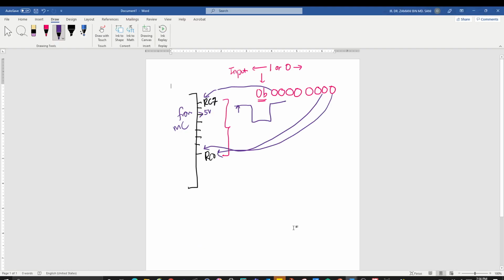So for example, just now here, if you are setting up this one as the input, right, the input here is input. So right now, this pin is waiting to get the signal coming in, and then it can do some processing. So the signal must also be 5 volt coming in. That's why you need to use a 5 volt switch.